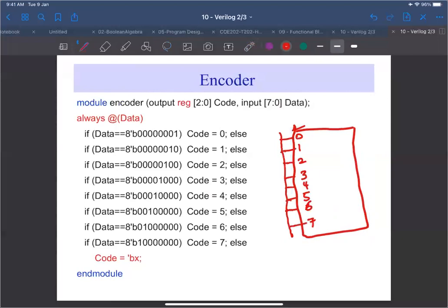This bus is of size 8-bit, and the 8 bits are splitting between the inputs of the encoder. So this is an 8 to 3 encoder, and your output is going to be 3-bit. This is bit number 0 of the output, bit number 1 and bit number 2. Then we have a bus that combines all of them, and this bus is 3-bit.